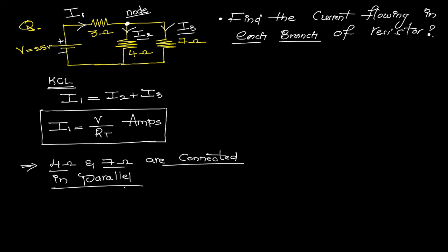So simply we can take, by solving this, finally you are getting the response as total resistance. With the help of this particular 4 ohms and 7 ohms, it means 4 ohms and 7 ohms both are connected in parallel, so to get the value of total resistance, you are going to get 4 into 7 divided by 4 plus 7.